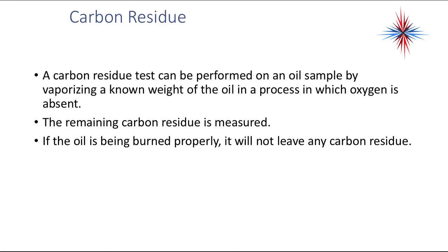Carbon residue is another property of oil. A carbon residue test can be performed on an oil sample by vaporizing a known weight of oil in a process in which oxygen is absent. The remaining carbon residue is measured. If the oil is being burned properly, it will not leave any carbon residue.